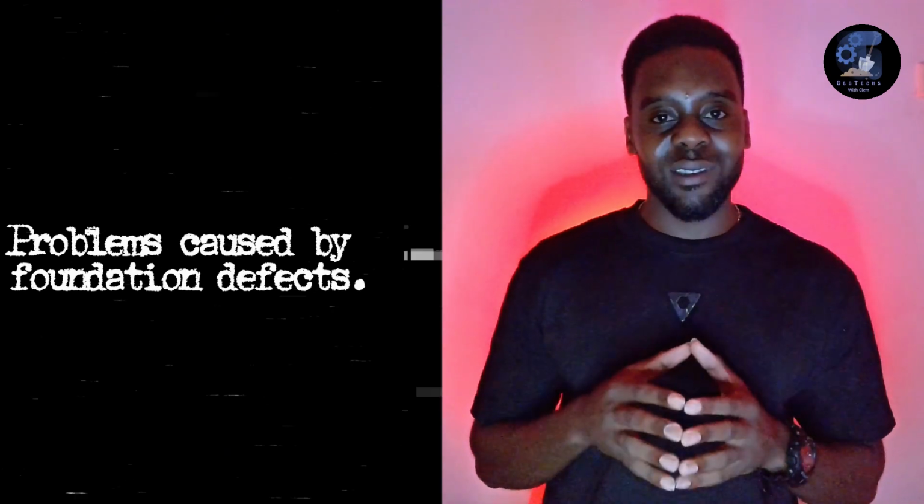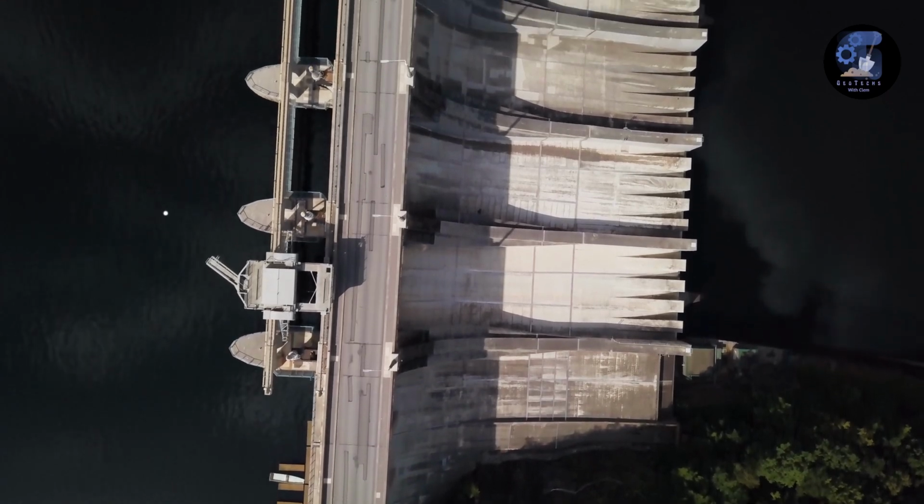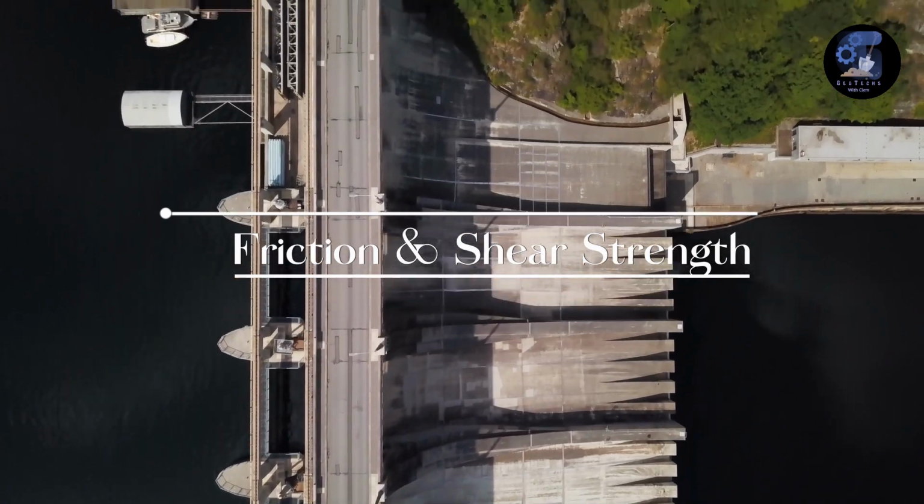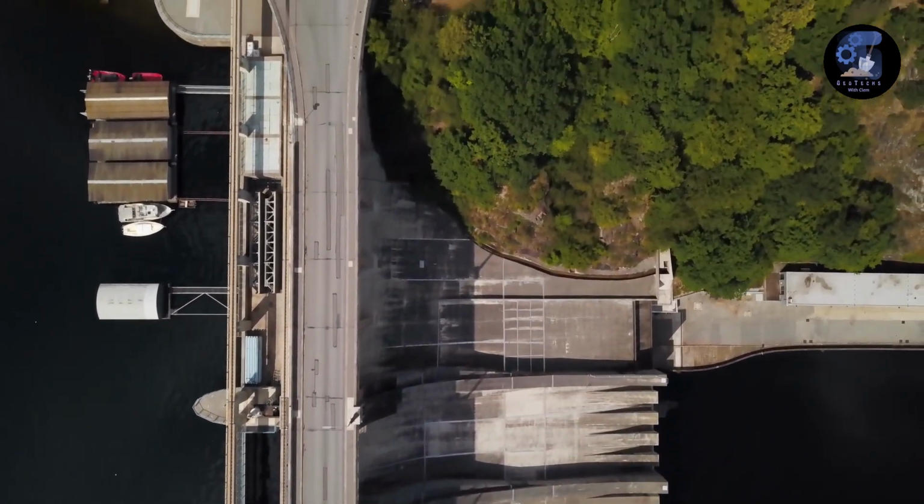In theory, the idea behind a dam is to stop and accumulate a huge body of water. However, water carries a huge force. Therefore, the idea is that the net horizontal forces acting on the gravity dam do not exceed the frictional resistance produced between the body of the dam and the foundation. If the frictional force is less than the horizontal hydraulic forces, sliding failure occurs. The resistance may be due to the friction alone, or it may be due to a combination of friction and the shear strength, depending on how the dam was constructed.